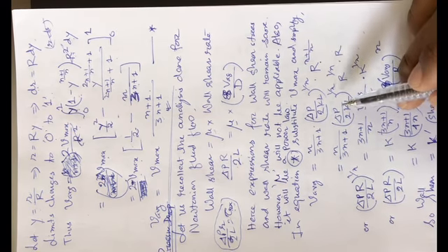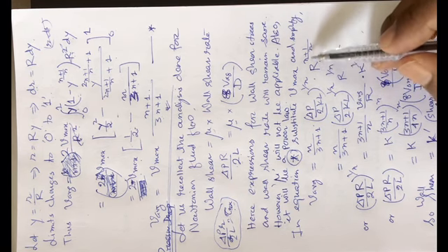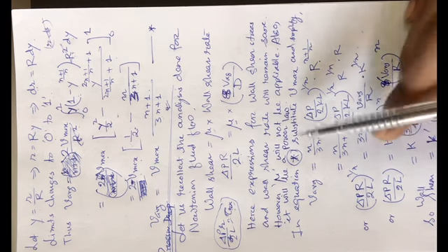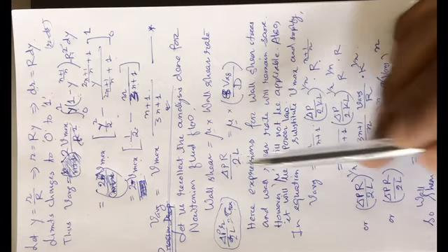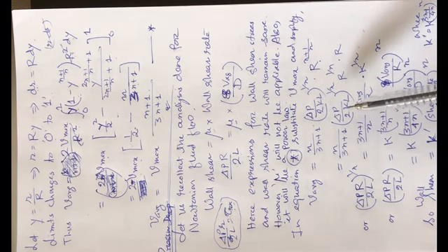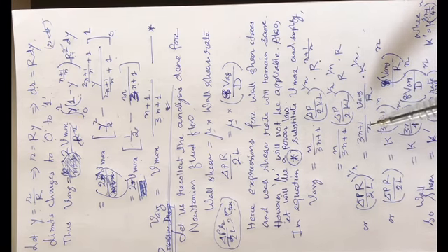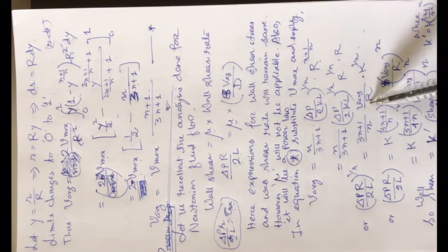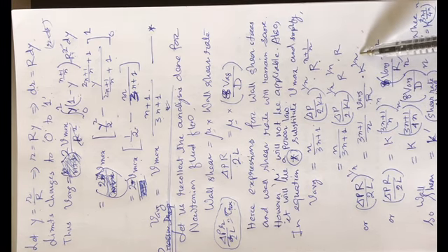Basically, this R we are breaking down to R to the power 1 by n into R. Similarly, k is an additional term as compared to the expression here. So we are taking out this term from this side, so k has to remain separately. We took out k. Then delta P R by 2L to the power 1 by n is equal to 3n plus 1 by n. This got inverted. V average divided by this R comes to the denominator, and k to the power 1 by n, which was in the denominator, is coming as the numerator.